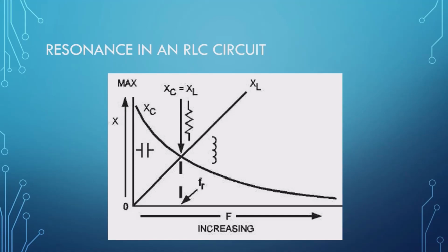No matter what the value of a capacitor or inductance is, there's a frequency, and we'll go through the functions, at which it will pass through all of the power or signal applied to it. If it's below or above that frequency, it will tend to degrade that signal by orders of dB. When we're building filters, we're always looking for a 3 dB or greater drop in the signal, just to block out the unwanted signals.